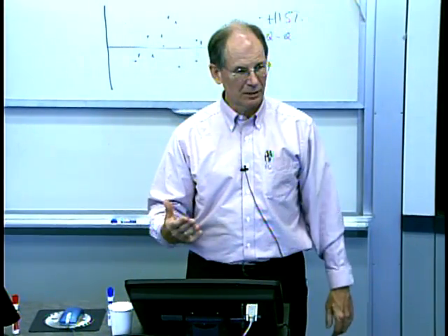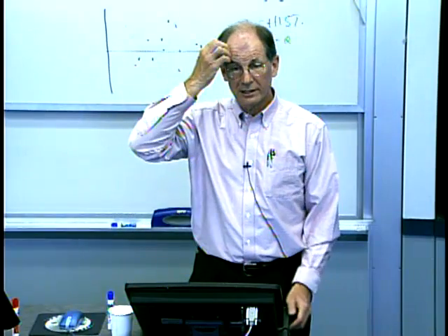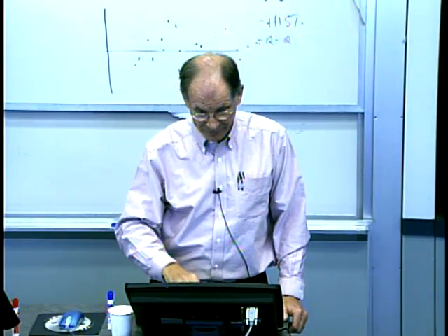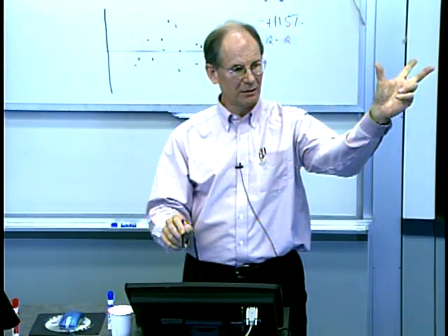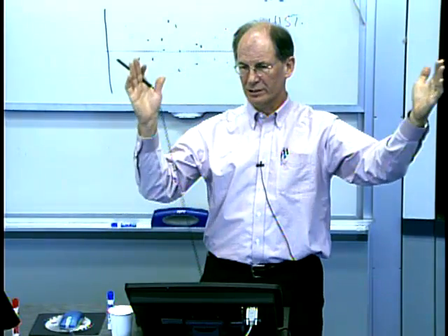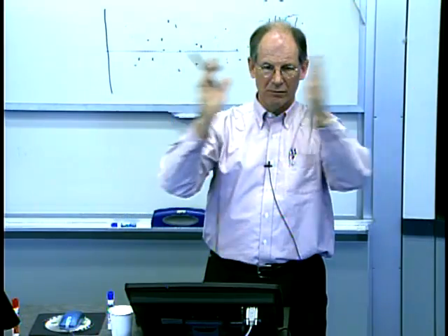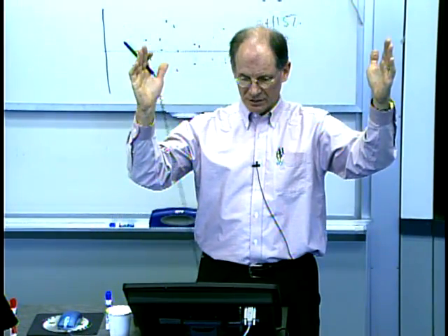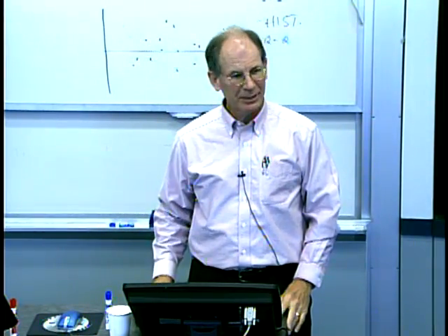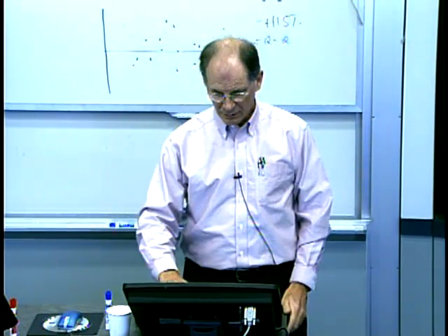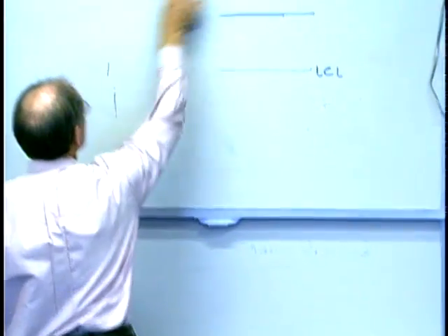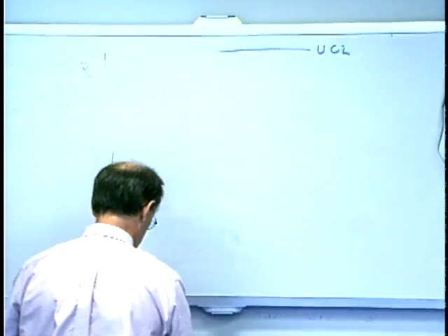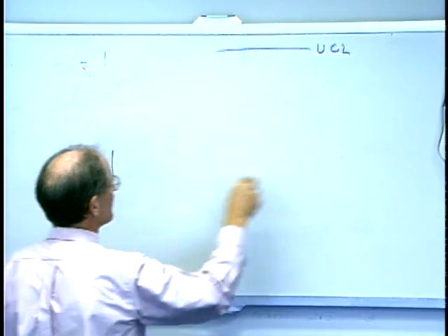Again, to try and give us a more common basis for this, things like this have been defined. The Cp parameter, process capability, which basically says what's the ratio of the width of that window to my plus or minus 3 sigma width. So is the variability of my process similar to or different from the desired? But it compares ranges only. And if you look at this carefully, that could say that I could have the following. I could have a process where these are my specification limits.